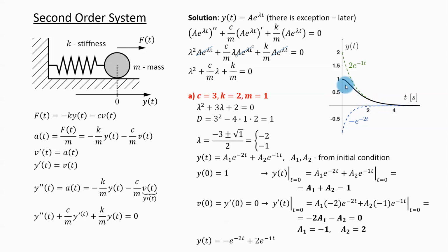You can see that the ball starts at 1, as per this initial condition, and the initial derivative appears to be 0, as per this initial condition. And then you can see that the ball exponentially comes to rest at position 0. You actually get this type of behavior when the friction is sufficiently strong in comparison with the stiffness of the spring. If the friction is sufficient, the ball will just come from some initial position to the 0 position.